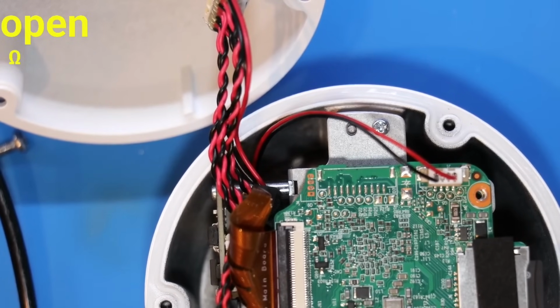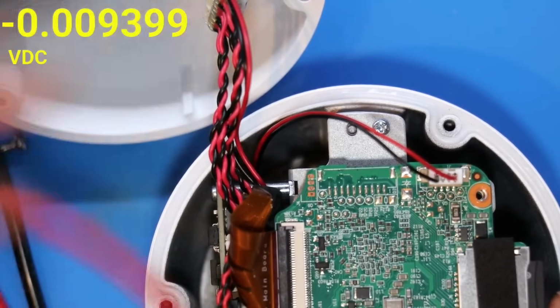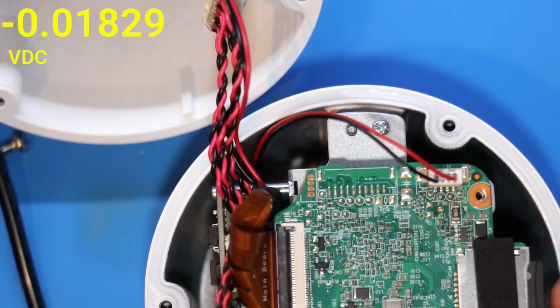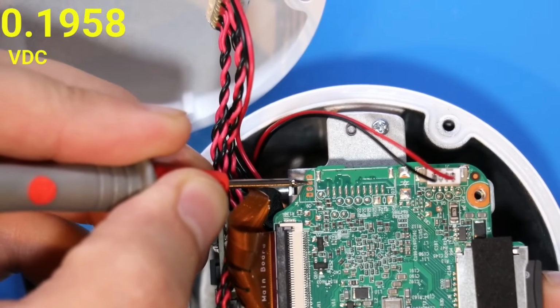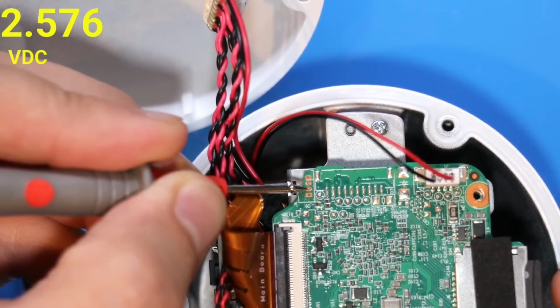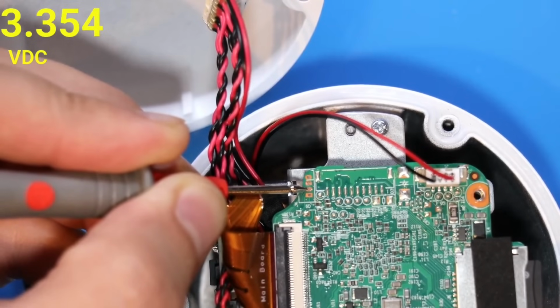Now we're going to change over to voltage mode, and I am going to power on the device. I'm gonna be off screen here with my hand, powering on the device, and then I'm gonna quickly come over and see if we can find where the UART is. Okay. So we're good, we powered on. We're at 3.3 volts. That one seems to just be holding steady there. And that one you see jumping around. That is a telltale sign that we have found the transmit pin.